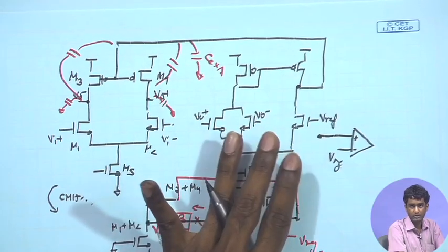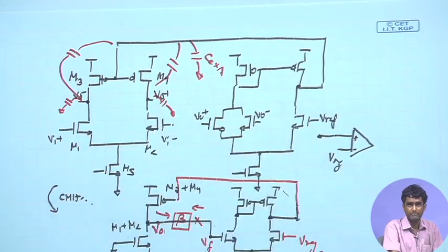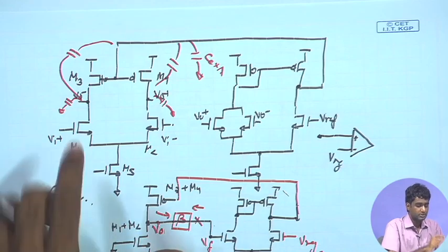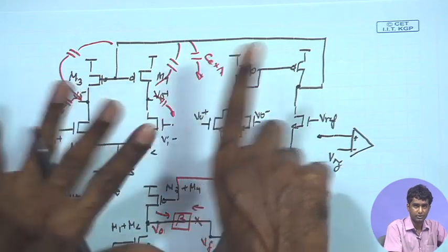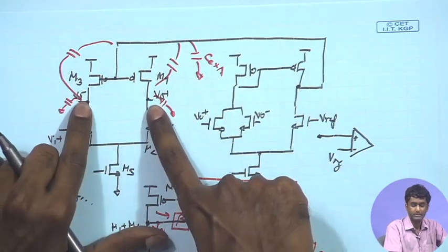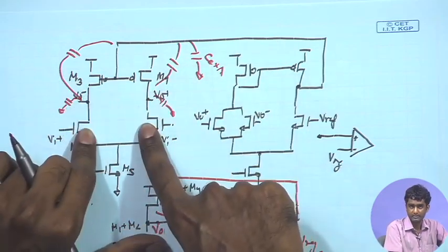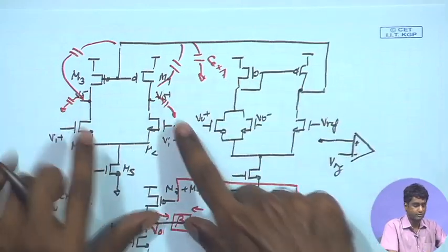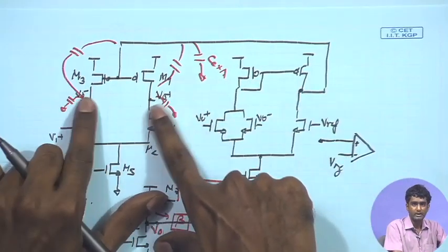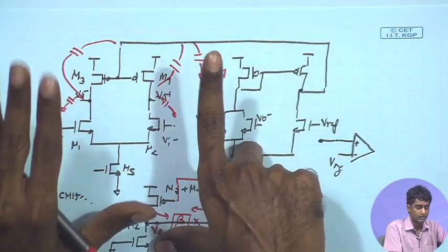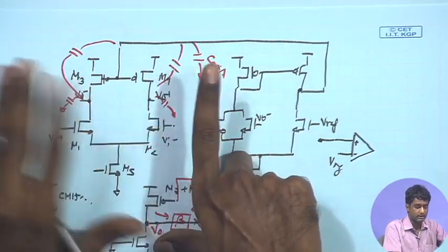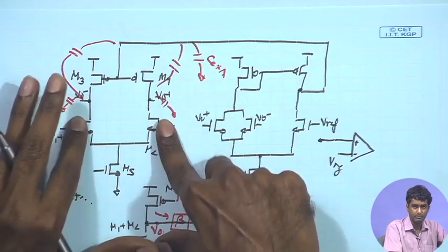It can be much slower as compared to the main amplifier. We should just take care that the additional capacitance coming at this differential node is not limiting the bandwidth of the main amplifier further. We will see that for the overall differential operation anyway, we will be using a compensation capacitor for the differential operation also, and that intentionally does limit the open loop bandwidth of the main amplifier.